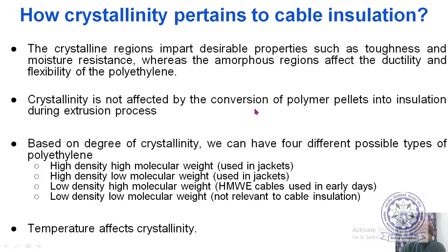Polymer pellets means small, round, look like tablets actually. So, all polymers actually before extrusion, they are made into pellets. Actually, these pellets are used in the extrusion process. So, these pellets can be easily packed in bags, and then they can be easily transported. And these pellets will be used and heated up. When they heat and they melt and they become together, forming a gel-like structure.